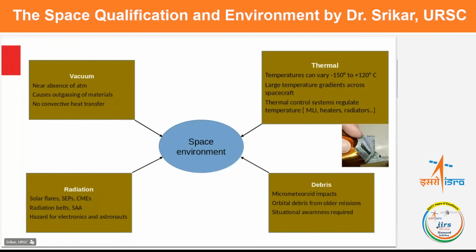That golden colored cover, the envelope that you would see on the spacecraft if you have ever seen any photographs of a spacecraft. That gives you an insulating layer where it will reflect off several of these solar radiations, and then trap the heat if needed. And if you want to increase the heat somewhere, there is the employment of heaters, and then radiators that will radiate off the heat to cool and reduce the temperature. So thermal management in space to maintain the desired temperatures is a huge task, and it is done for all spacecraft and space assets, and it is essential.